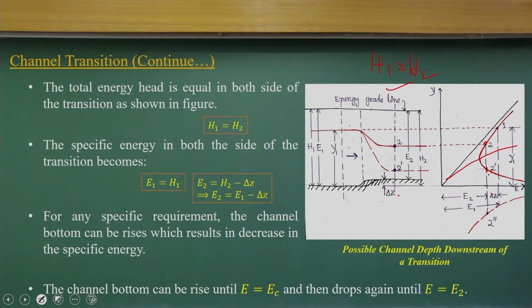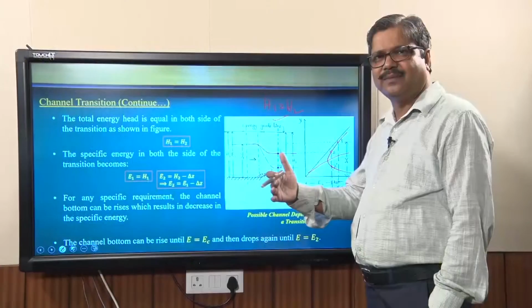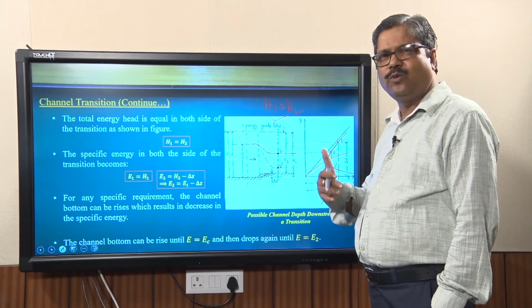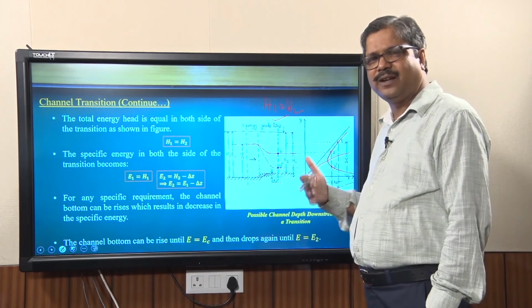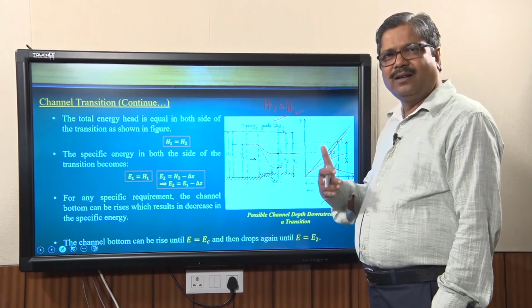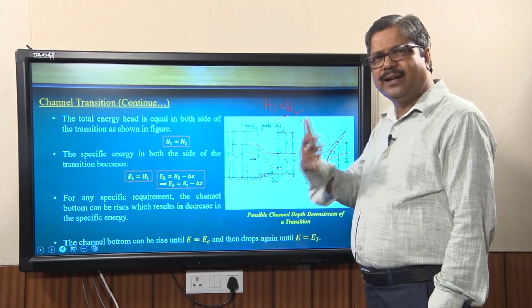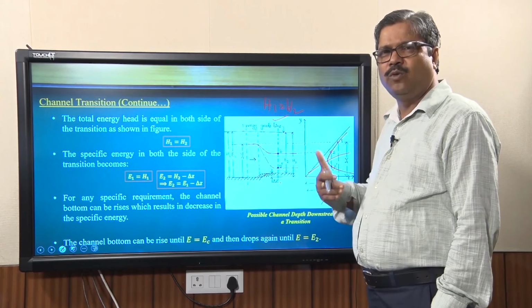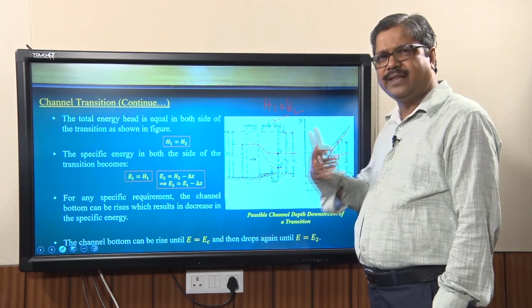subcritical. So one lies here, the flow is subcritical. The 2 is a possible solution for us, because the flow will try to remain in the same regime, the subcritical regime. As we discussed earlier, when the flow changes from supercritical to subcritical, there will be some sort of energy dissipation, or it will go through the critical flow depth. It cannot happen suddenly